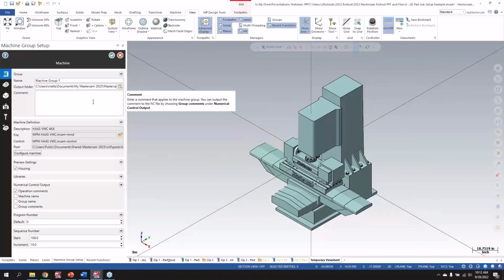The nice part about Mastercam, as it's always been, is I can make the file as simple. I don't need any work holding. I don't necessarily need to define a stock. I can just slap some wireframe on, get a toolpath, and get it out to the machine as fast as possible. But on the flip side of that, if I do want to set up all this stuff, this is kind of walking me through that process of what I need to do to get everything fully set up, so I have collision avoidance, all that sort of stuff.